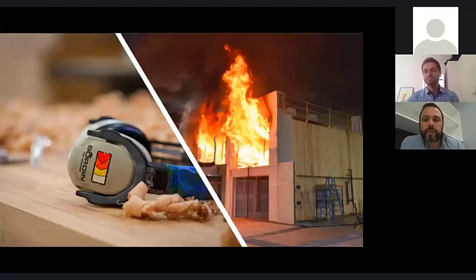And it's a good point, Nate, because when you talk architecturally, I honestly believe that your hotel is a really good opportunity to potentially expose CLT, and you can achieve acoustic and fire rating requirements if you've got a single wall, which would normally have direct fixed fire plasterboard to it, and have your false wall on the other side. There's an opportunity there to run that as exposed. It needs to be fire engineered. You need to consider that. But there is an opportunity to do that. I'd probably lean towards that rather than the soffit.